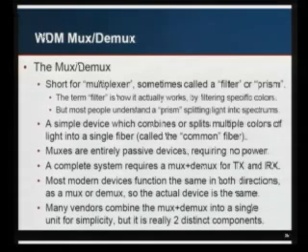Any complete system requires a mux and a demux. On most modern systems, they're the same piece of hardware, but you need both components. You need one which combines the signals from all the different spectrums, and you need one which filters it, because if you just sent the same light to every receiver, the receivers are wideband. They would see all the light, and they would see 5, 10 different signals, and they would be confused. So you need something to actually filter and split the light signal on both ends. Sometimes people ship them in a single box or a single unit, but it's really two distinct components inside for simplicity. If you're operating over a fiber pair, you need both sides on both ends.